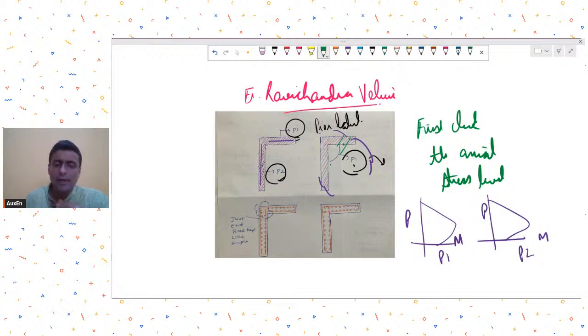In that combined PM interaction curve, it will algebraically add up the axial forces and find out the equivalent moments. So if you are giving a single pier label, it is going to treat it as a combined section and then do the calculations. Now this approach is risky if the actual stress levels are different in these two legs.